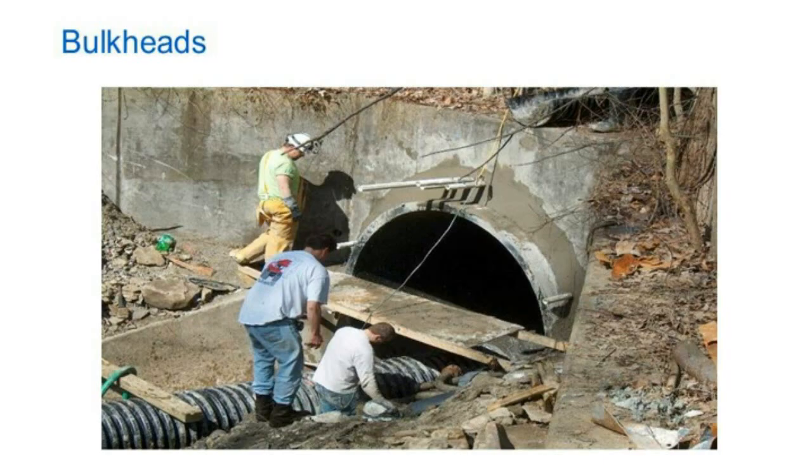Okay, as we move on and we build this bulkhead, or as we're constructing it, we have to install vent tubes. Those were not installed. Those vent tubes are just basically going to be a little bit longer than the bulkhead itself. So those can be placed in at the time of building the bulkhead. We have to have a way for the air to get out of the annular space to allow the grout to flow properly throughout that annular space.